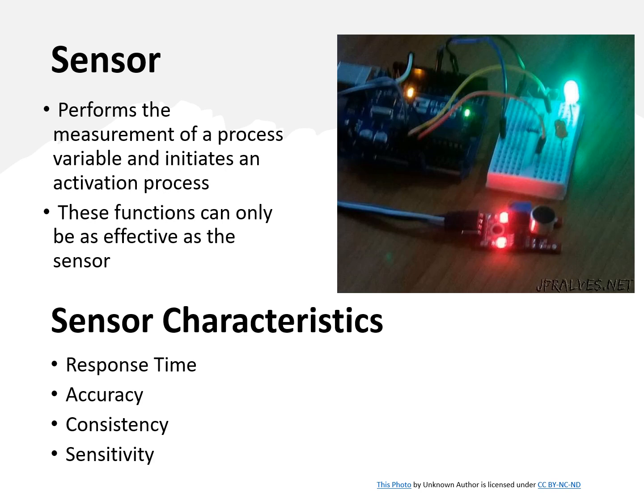Response time. This property of the sensor describes its ability to respond to a change in the measured variable. This can vary depending on the type of the variable that is being measured. Pressure and temperature measurement might take a bit longer compared to a liquid level measurement. The response time property is very critical when the process control loop requires a fast response to changes in the measured variable.